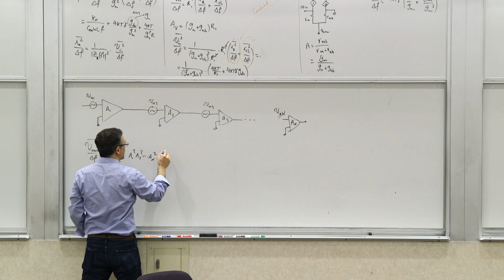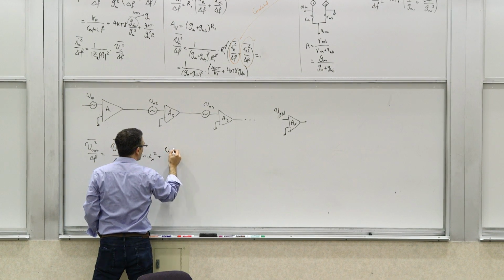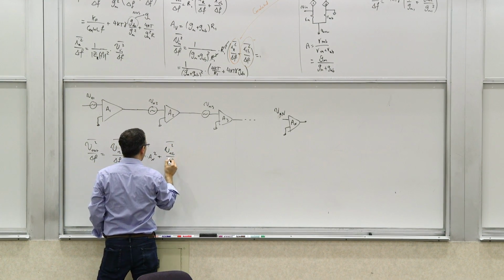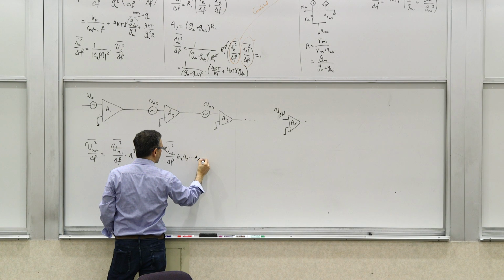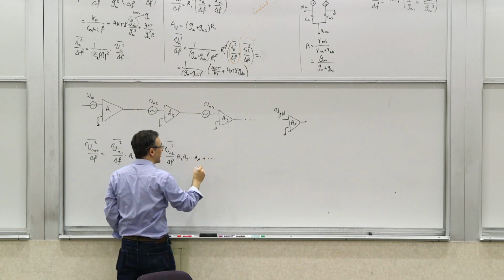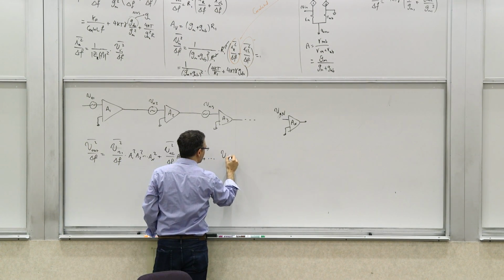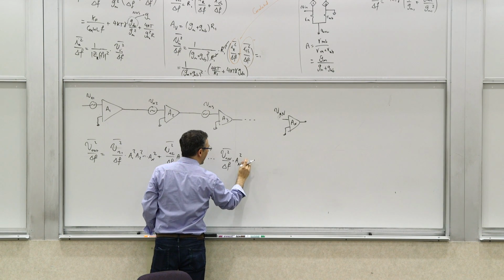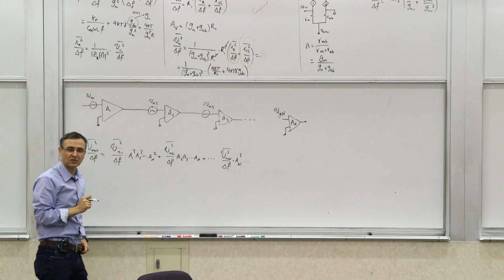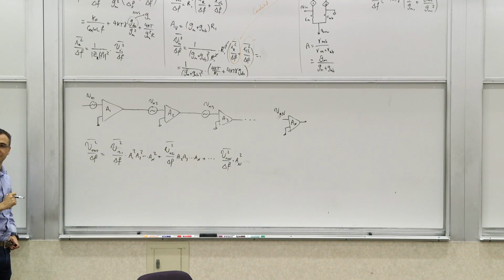The second one goes through all of them except for A1. So you start with A2, A3, all the way to An, and so on and so forth. The last one, Vnn, would only observe what? The gain of the last stage. So that's the total output noise.